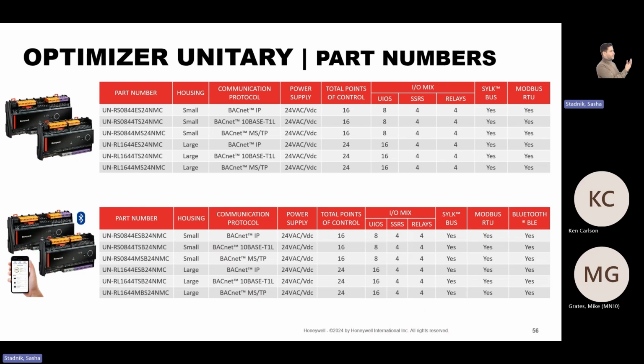That is a pre-wiring validation application. Can I add Bluetooth to an existing controller that doesn't have Bluetooth? No, you can't. There's no way to do it. We know Belimo and the rest are using a dongle. That highlight is going to go away because no one wants to use a dongle, because it creates a cybersecurity problem. Okay? That is another thing.